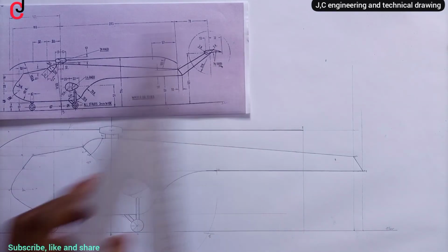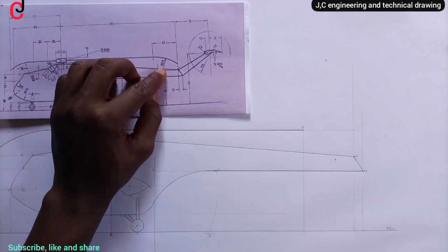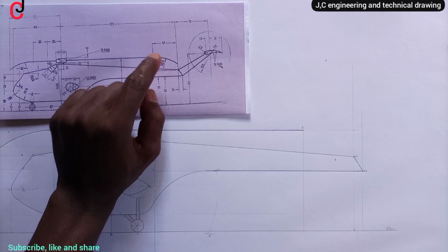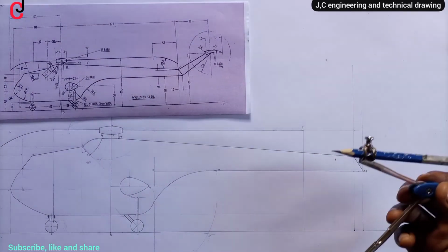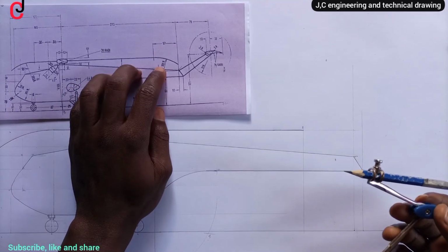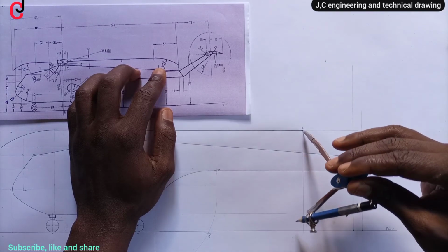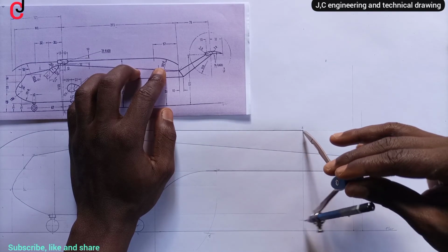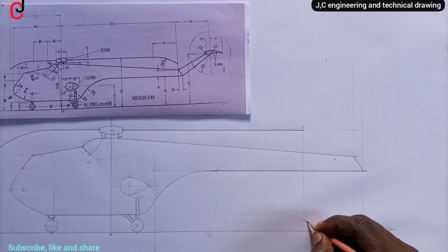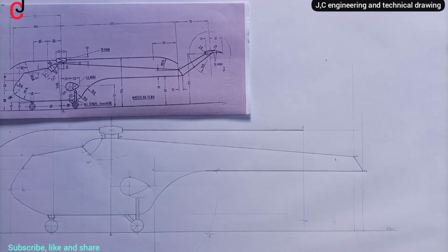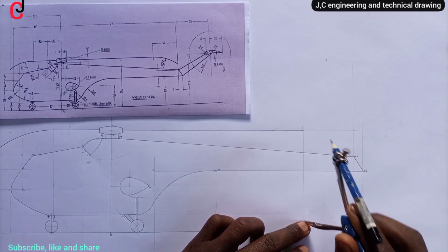Then we'll stop. Then we'll open our compass to 102 millimeter radius. So we succeeded in picking our compass to 102 millimeter radius, place it at point X, scribe an arc down, then it intersects our vertical line at point X2 using point Z2, still on radius 102 millimeter.